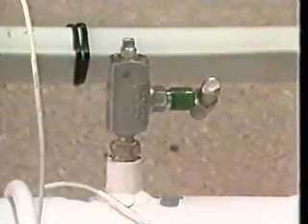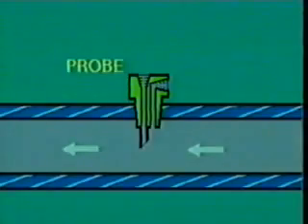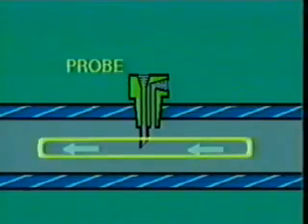Once a sample point has been located and a tap installed, a probe should also be added. A probe is usually a stainless steel tube installed in the line which has a beveled end aimed upstream to gather the sample. Because of the nature of flowing streams, both gas and liquids, the sample should be taken in the middle third of the pipeline.